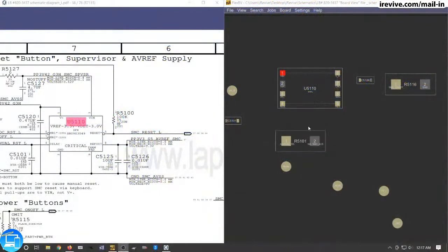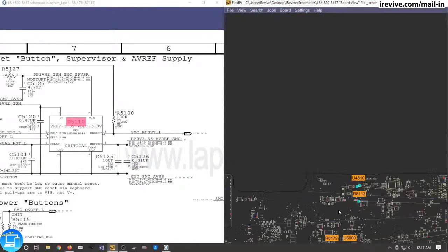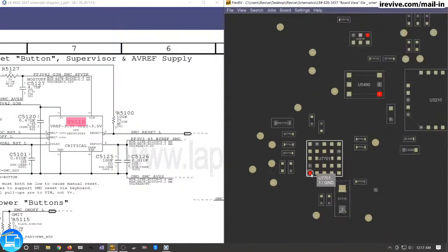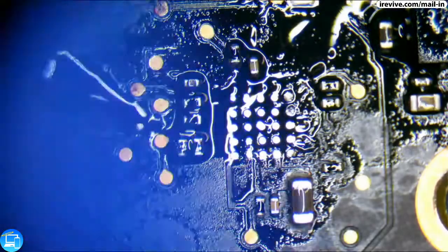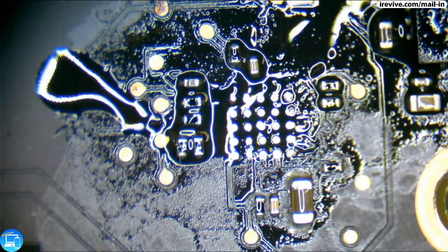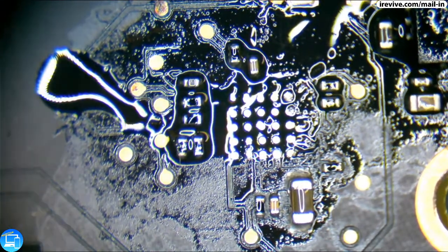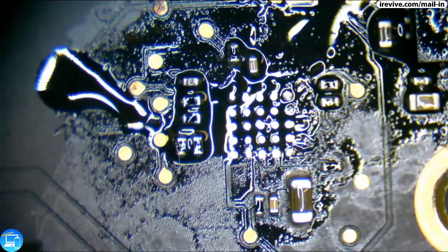Okay, so now that I have it out, just to give me a quick refresher, let's look at the orientation of this specific driver. Looks like pin 1 is going to be facing in our bottom left, so our dot is going to be facing in the bottom left as well. Change back over to our microscope camera, and let's get our driver lined up and prepped to be reworked back into place. Reflow has such a negative connotation now.